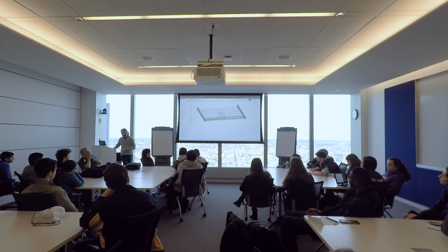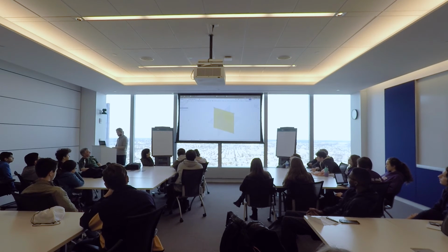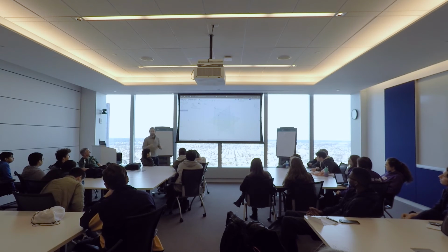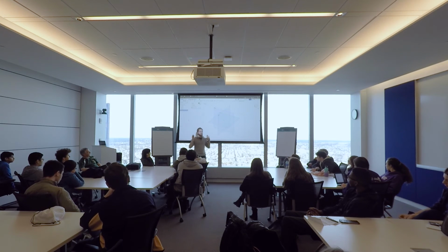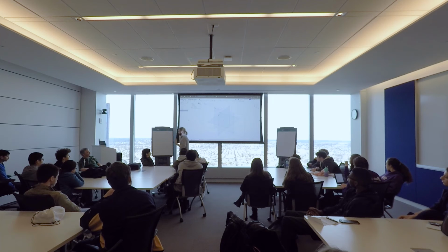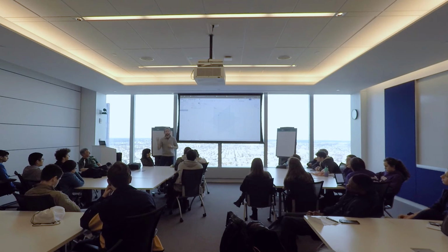I'll just make a new part studio here to do this. So pneumatic cylinders, the cool thing about pneumatic cylinders, they have 2 positions, right? Generally, I mean, you could buy a 3-position cylinder, but generally pneumatic cylinders have 2 positions. You have an extended position and you have a retracted position. So you can use those 2 positions to figure out exactly where an arm would be and where it would end.